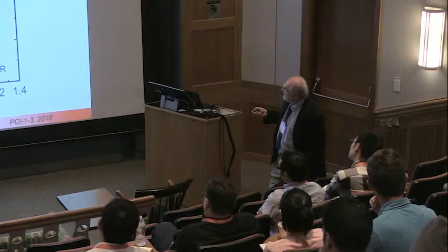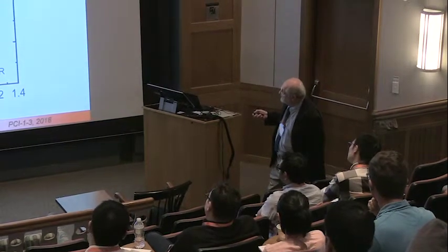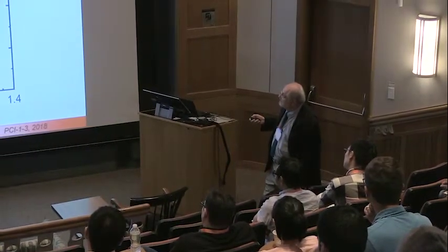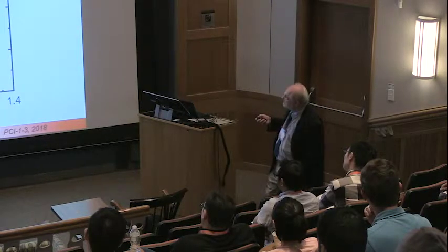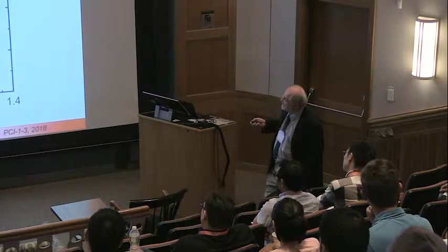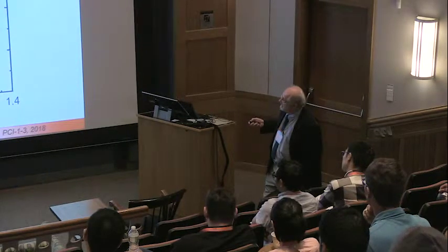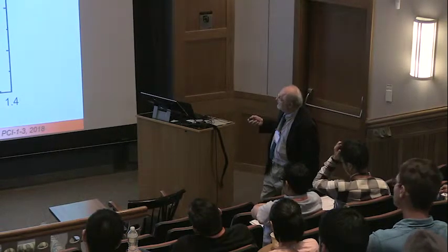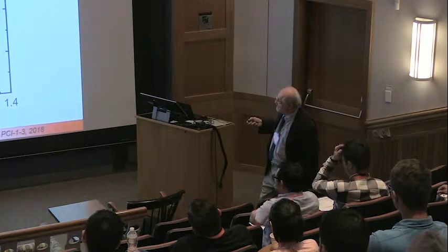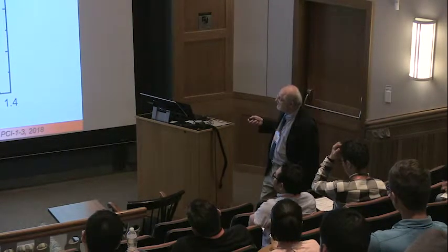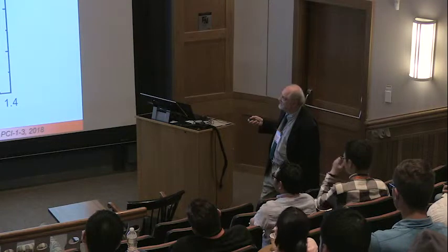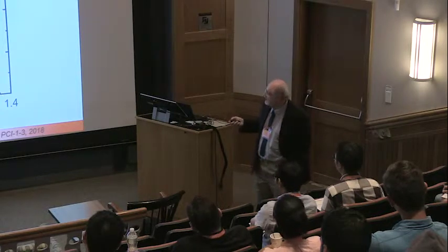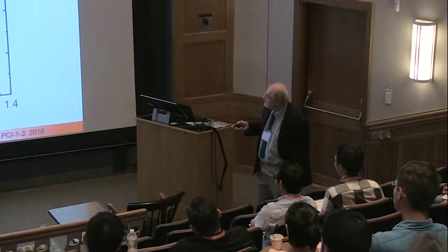So if you look here at the actual engine with all of the losses that we discussed before, if I increase the boost pressure up to 3 bar instead of the normal atmospheric naturally aspirated 1 bar, I see a boost in my efficiency, my net efficiency, by a significant amount, as much as 10%. So this is very important from the standpoint of the overall engine system. You're not really changing the combustion that much. Your gross efficiencies are not changing as much. But what you are accounting for is the pumping and the friction becomes significantly improved.